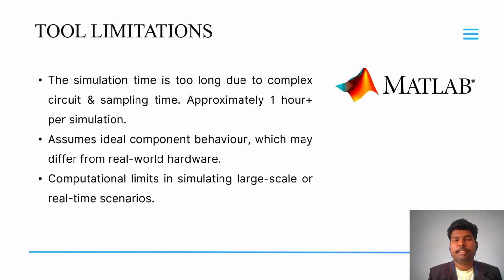For the tool limitations, first, the simulation time is too long due to the complex circuit and sampling time, approximately 1 hour plus per simulation. Second, it assumes ideal component behavior, which may differ from real-world hardware and prototypes. Third is the computational limit in simulating large-scale or real-time scenarios.